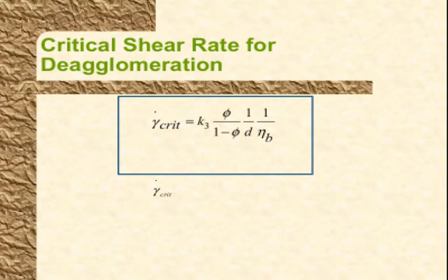In this case, all you are required to look at is how much shear I should apply for a given powder, polymer, and concentration combination. What is A, what is B? If I change those two, and if I change the ratio of A and B, how much shear rate should I apply? So at this point, you have a design equation.